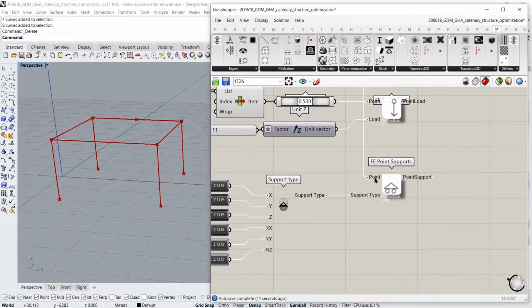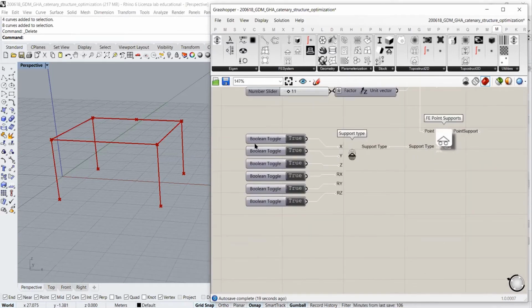So we are saying that the 4 start point here, the base points, are going to be fixed support. And then I'm going to also define these upper supports. We already have these 4 points. Now we can derive this point as the start endpoint of the beams or endpoints of the columns. It's easier to use the endpoints of the columns because the endpoint of this beam overlaps with, is coincident with the start point of this other beam.